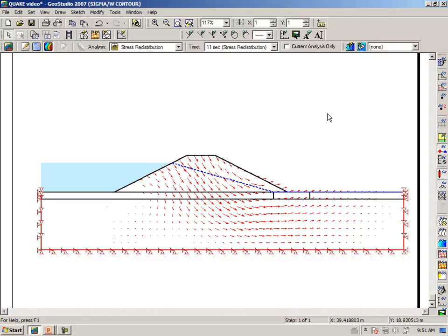However, the displacement field is very meaningful and realistic, and at this stage you could try altering your undrained steady-state strength, and if we were to cut it in half, we would likely get substantially more permanent deformation because, as I've noted earlier, the amount of deformation you compute is somewhat sensitive to the assumed undrained steady-state strength. I won't do that here.